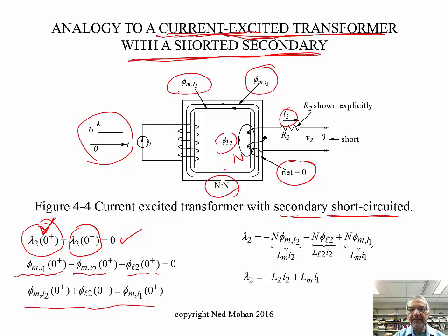And I purposely cut this air gap to resemble it more to a machine where you have a rotor and stator separated by an air gap, right? So that's why I cut this here. And also, in the rotor we assume the same number of turns as the stator. So n equal to n is not a bad idea here on both rotor and stator side.